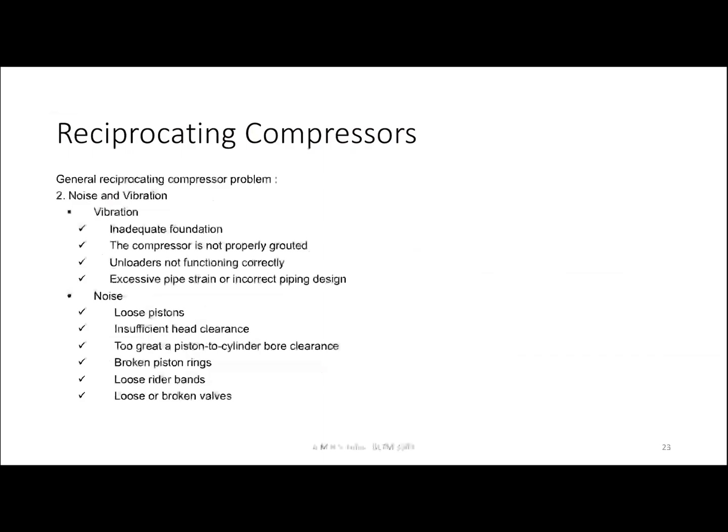Sometimes the compressor is not properly grouted, meaning the floor where you install the compressor is not strong enough. Or it can be because unloaders are not functioning correctly, related to the system, or because of excessive pipe strain or incorrect piping design. That's a typical cause for high vibration.